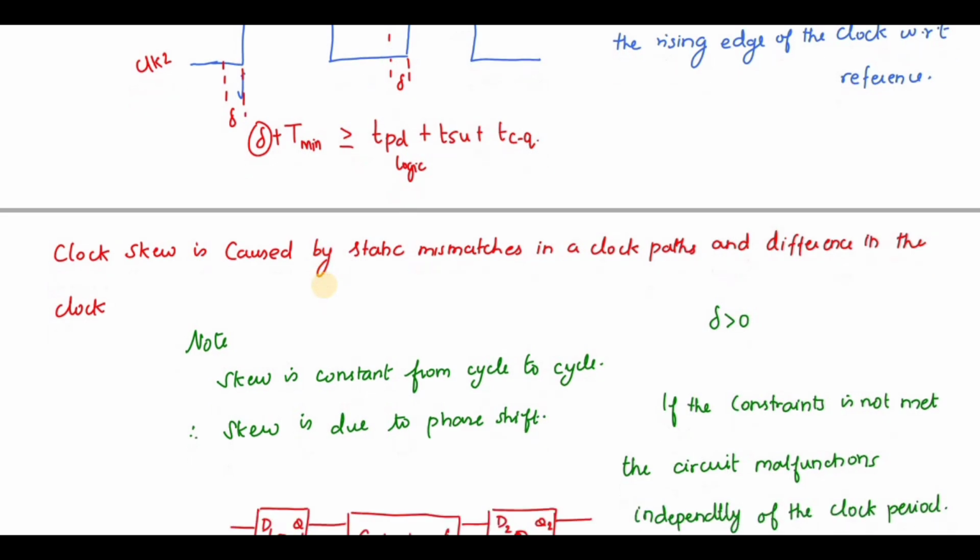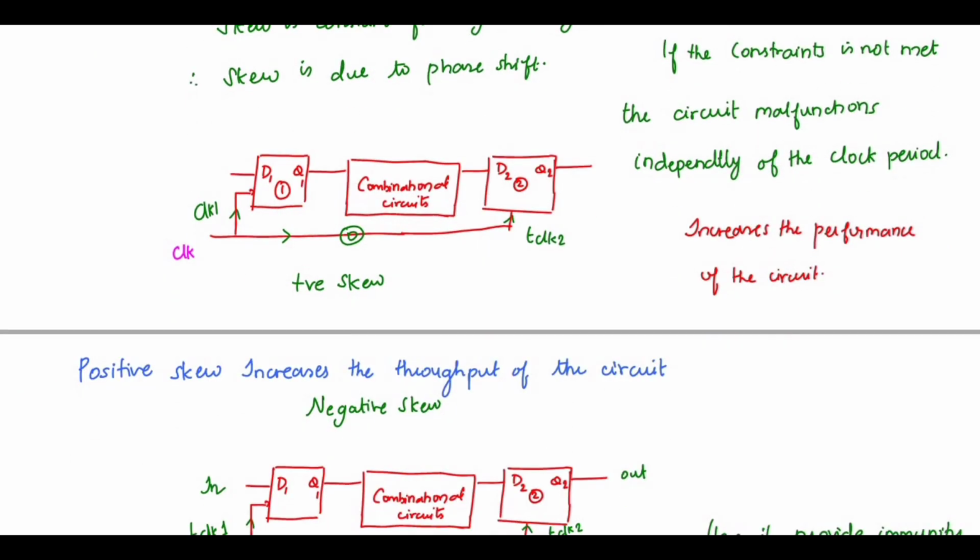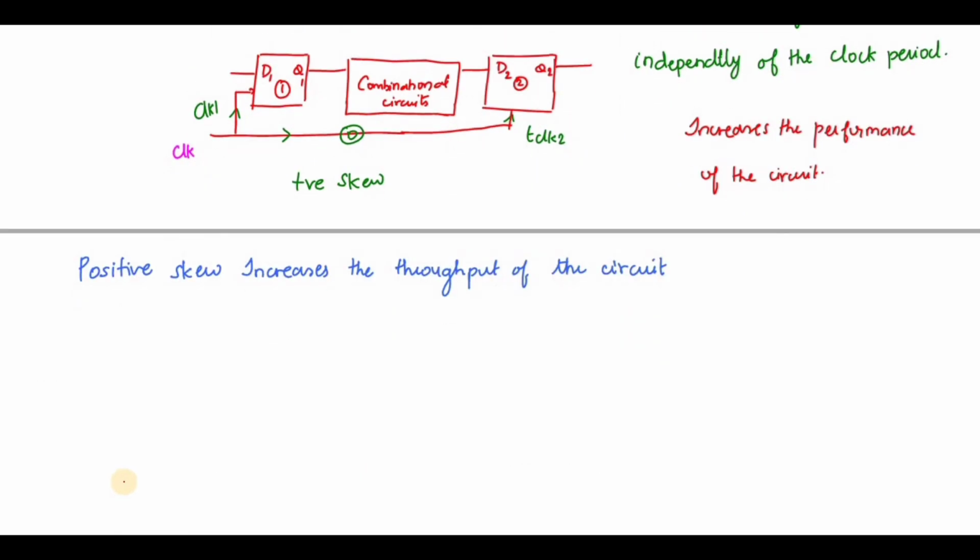Okay, so for hold time, I can write it as: T hold is greater than or equal to TCD of logic plus TCQ of register.